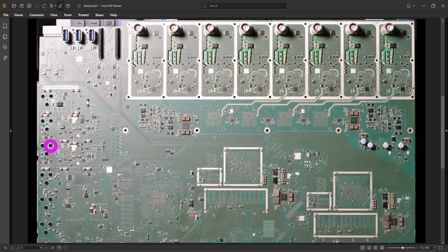And looking at the back of the board, you can see that the cage is extended to behind the BGA footprint as well. And that's because the vias connecting all the BGA pads go through the entire board, and they act like tiny little antennas, and they can radiate out all the digital noise into the board as well. So it's pretty important to cover all of that. There's also a clear break over here in the ground plane, and I'm sure the VDD planes between these two, because this is kind of the boundary between the mixed signal analog and the digital in the front end, because the data converters are over here.